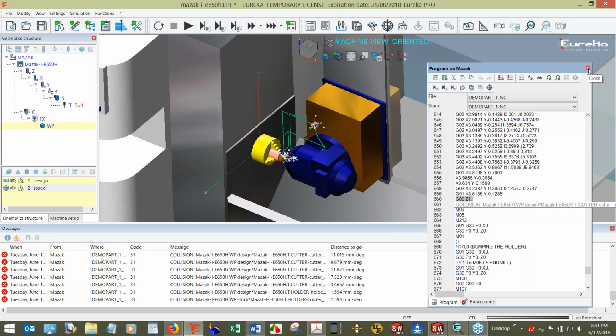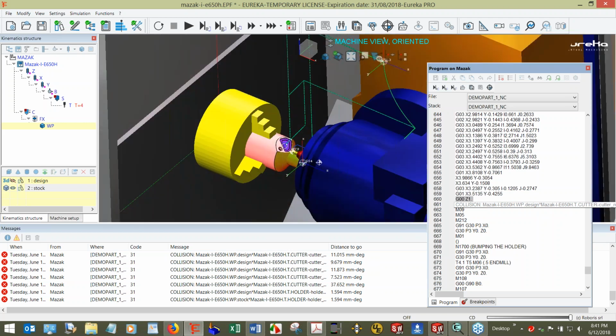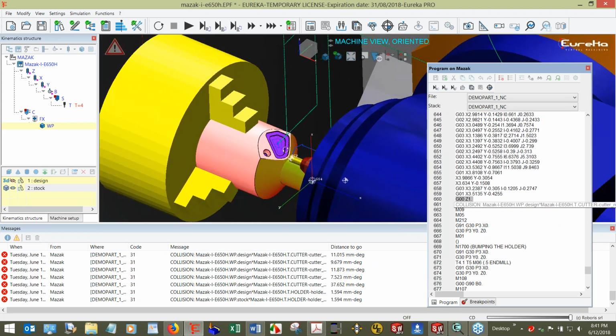They have an optimization where you can increase your metal removal rate, and that's one of the reasons why I chose the pocket move. Or if you have, let's say, a high feed mill where you cut a lot of air and have uneven cuts, facing or what have you.